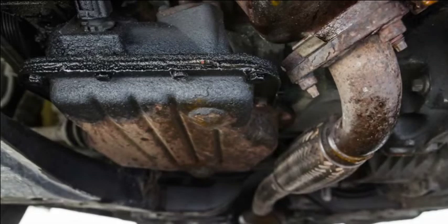Non-pressure leaks usually occur at component mating surfaces that are sealed with a cork, paper, or neoprene gasket. Some mating surfaces are sealed using form-in-place gasket, or FIPG, a specially formulated silicone gasket making compound. Repair these leaks as follows.